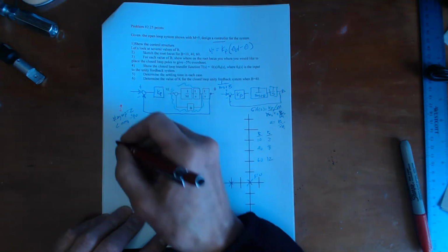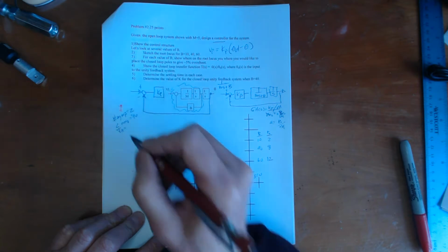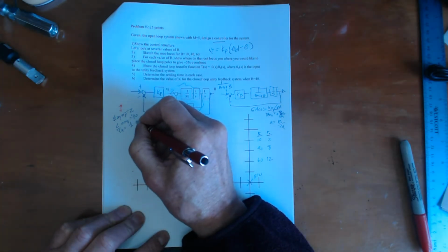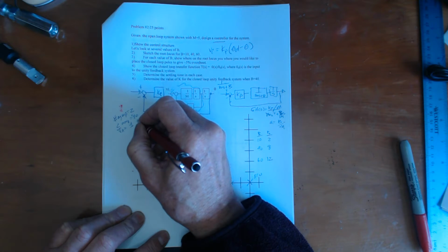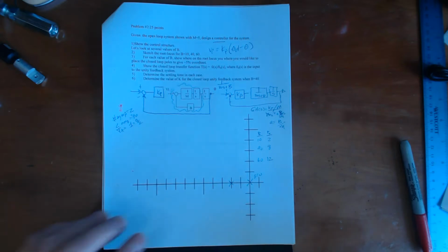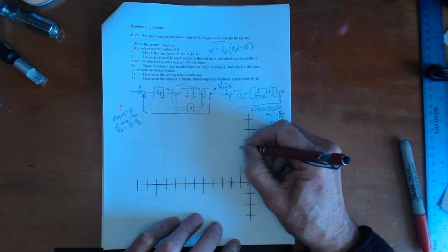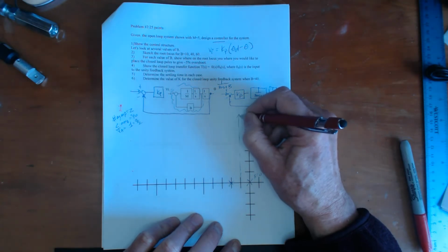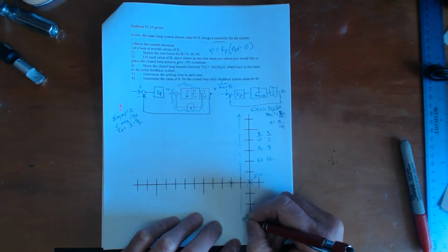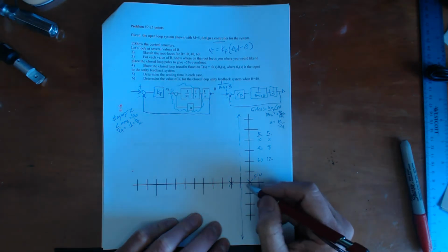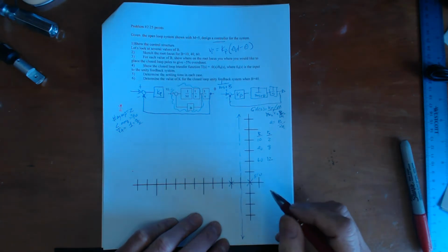And so we can look at where sigma A is, the sum of the poles minus the sum of the zeros. In this case, it's really just b over 2 is where it is. For second order systems, that's pretty standard. And so I can draw this root locus this way, and I will know that it goes up this way and it goes down this way. So there's b equals 10, and so when b equals 40,